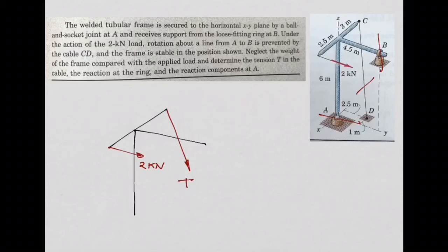At point A, it is a hinge, right? So a hinge means, if this is the column you have there, if I try to rotate about point A, that is possible. Point A does not move, it's fixed, but the rotation about point A is possible. You can see it from the pencil here: I'm rotating the pencil about point A. So that rotation is possible, which means no moments as reactions, because the rotation is allowed to happen.